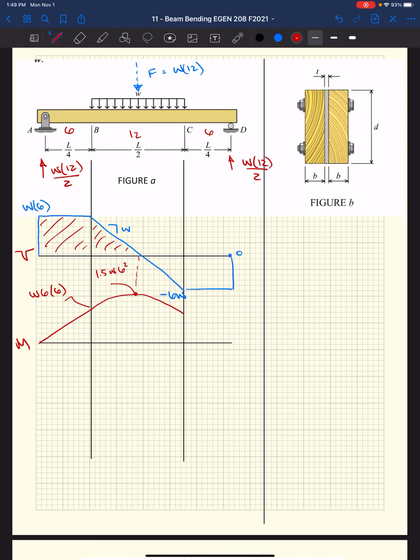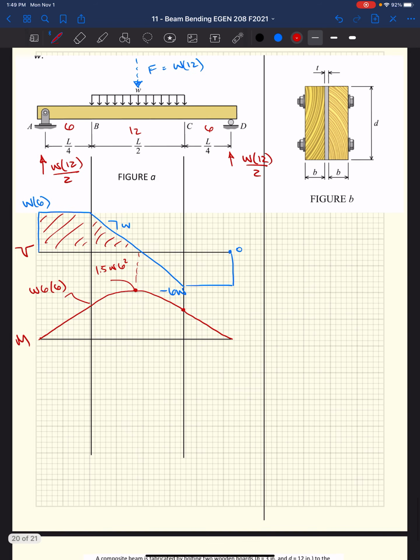Then we crest over and go down negative, and then we go back down to 0, right? Closes at 0. Same amount of area above and below our shear diagram, which means we're going to rise and fall the same amount with respect to moment, which is what we should expect based on having simple supports. We're assuming there's 0 moment, which is good.